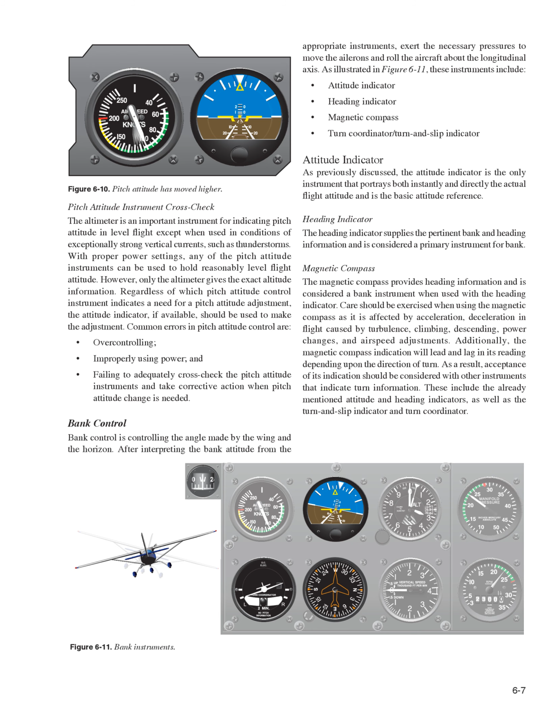Care should be exercised when using the magnetic compass as it is affected by acceleration and deceleration in flight caused by turbulence, climbing, descending, power changes, and airspeed adjustments. Additionally, the magnetic compass indication will lead and lag in its reading depending upon the direction of turn. As a result, acceptance of its indication should be considered with other instruments that indicate turn information.